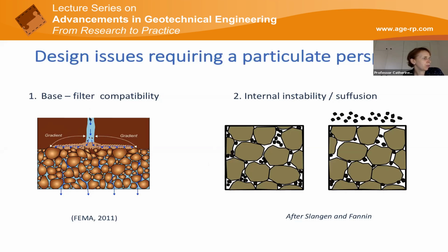Water is seeping through the core, and if a crack was to develop, you don't want that crack to develop and cause a preferential flow path through the center of your dam. So you have a filter downstream of the core, and the job of that filter is to stop the particles from moving and prevent this crack from propagating into a major breach in the dam.